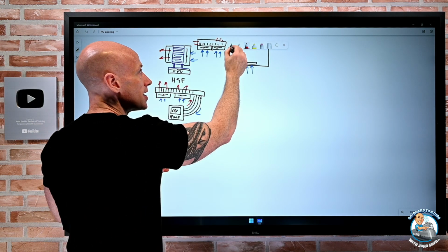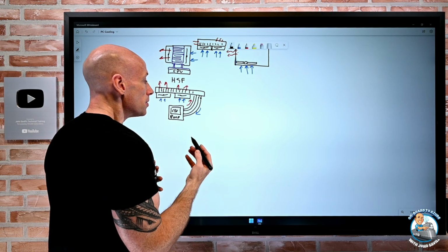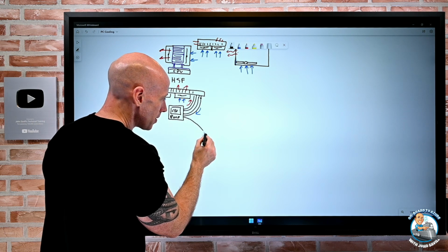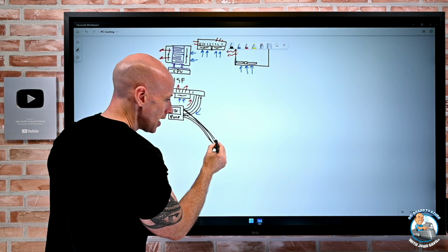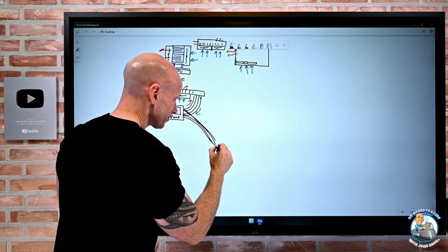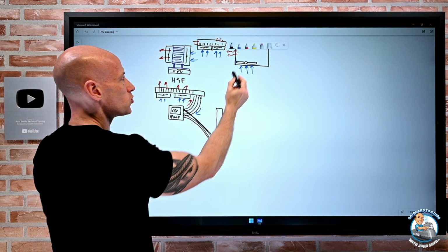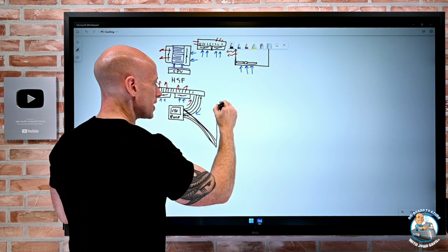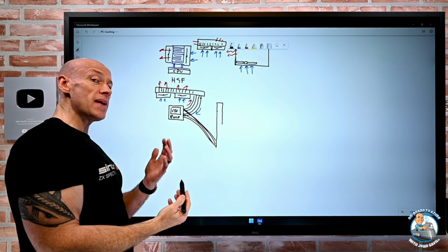The other orientation I could have this would be at the front of the case. So my other thing I could do is, instead of those pipes going there, they could maybe go down to the bottom of the case. And I still have that radiator. I've got the radiator here. Now I want to be careful, I'm drawing that poorly, because I need to make sure the radiator has a point that's higher than the pump. There might be air bubbles.